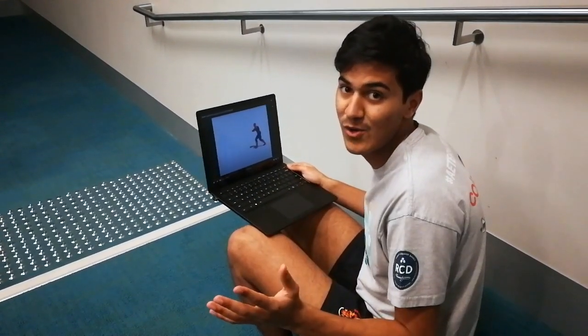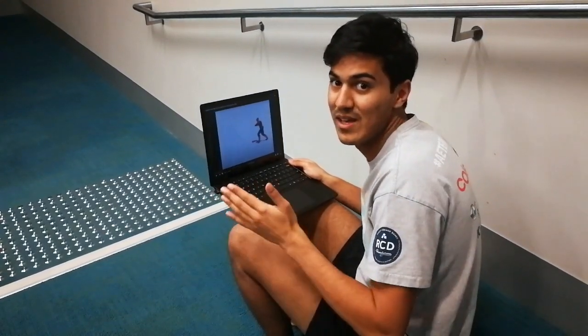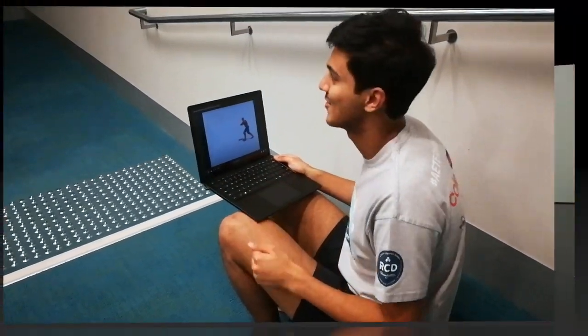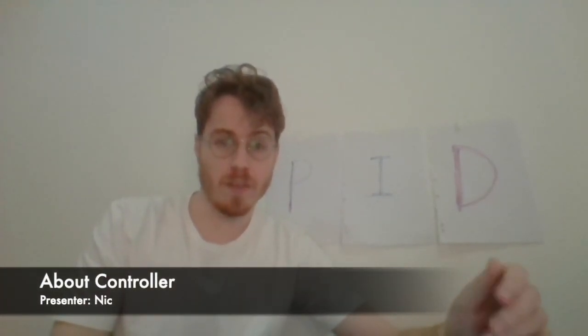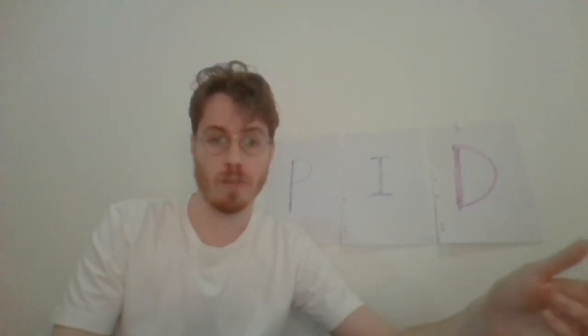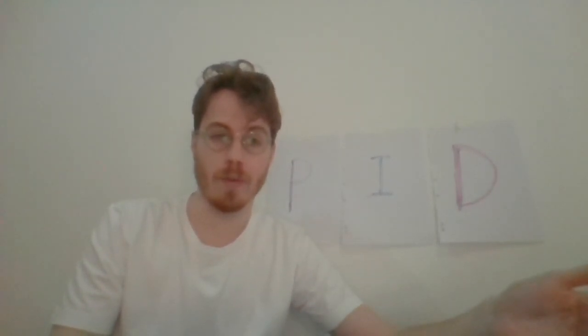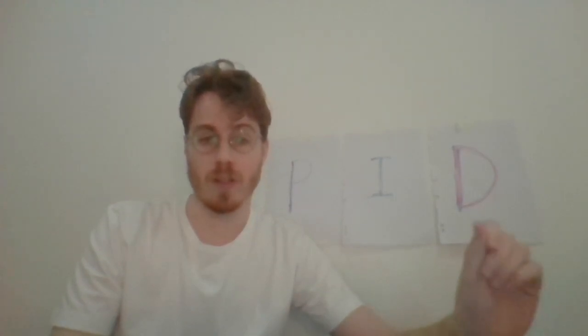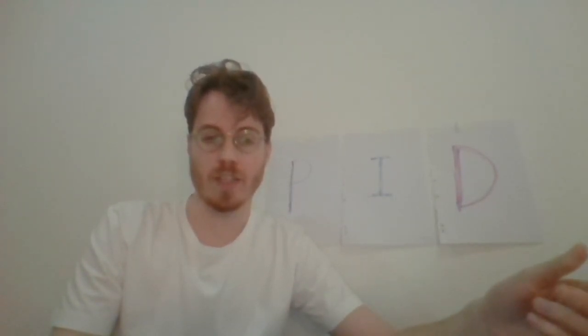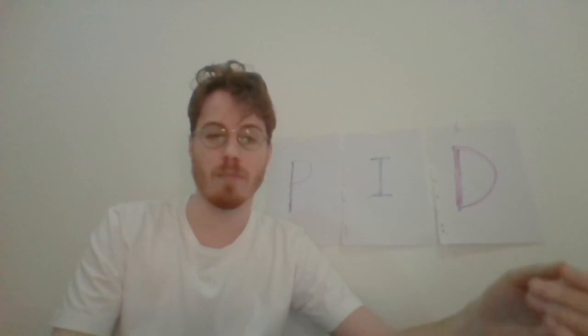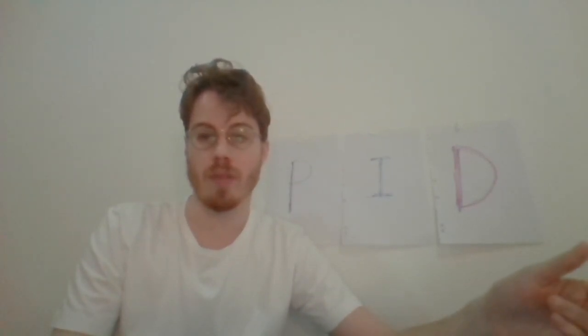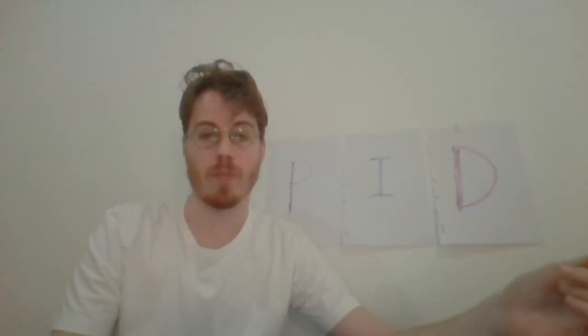There were plenty of other algorithms that we could have chosen, but this is the way that we chose to go. We considered lots of different ideas for the controller, from full state feedback to proportional control. We started with PID control since it's simple and reliable. We held the speed of the robot constant and instead took control action on the angular velocity based on the misalignment of the robot with the path and its perpendicular offset from the path.